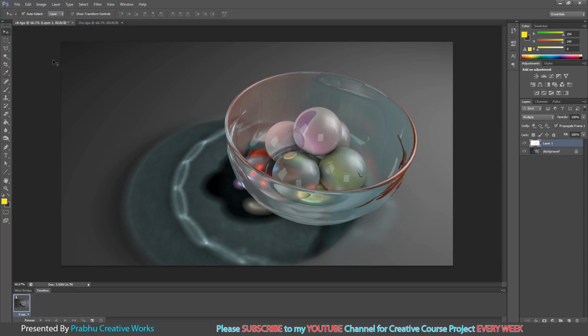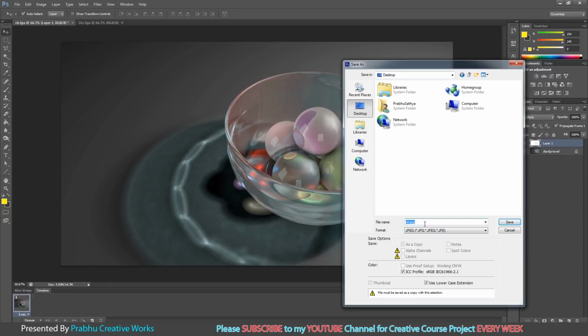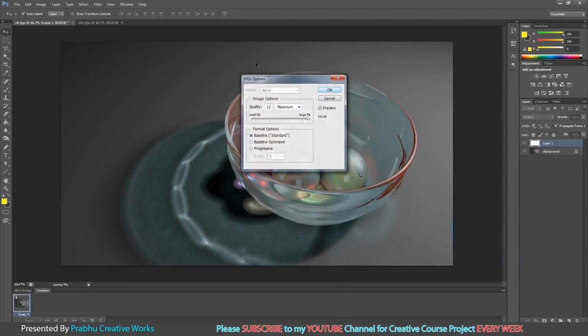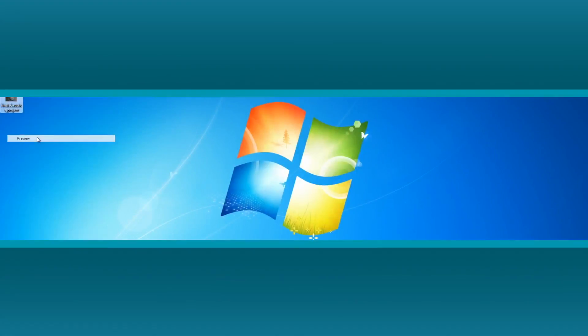Now you want to save this scene, so go to file and choose save as. I will choose my desktop, and choose JPEG. Name it final underscore caustics project. I will give save and give quality to 12. I will close my project, go to my desktop, right click and choose preview.